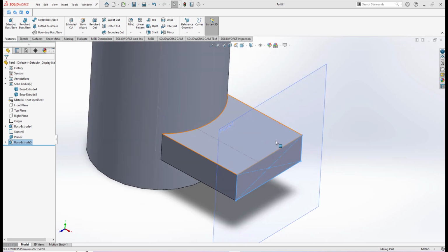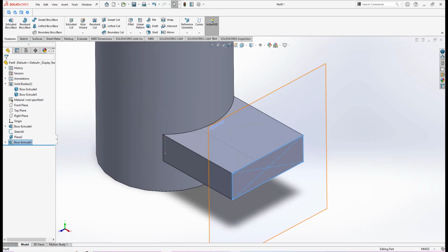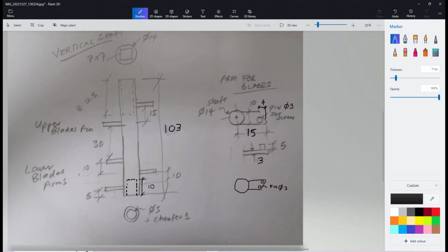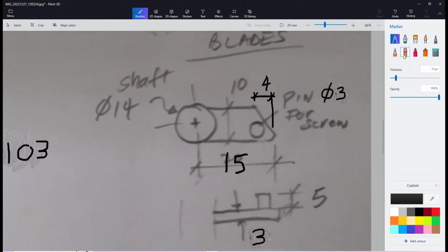Alright, the next move, if you look in this sketch, actually I do a modification here. This must be 2 units. So at the corner here, they kind of like have a cutting, so I will do chamfer by the distance of 2 and this thickness is 10.